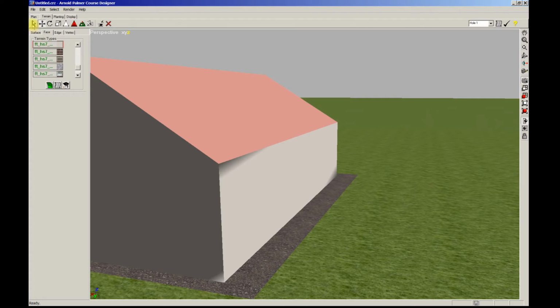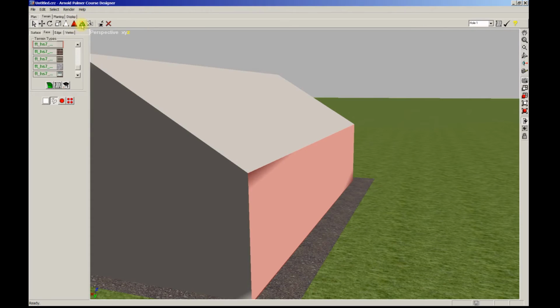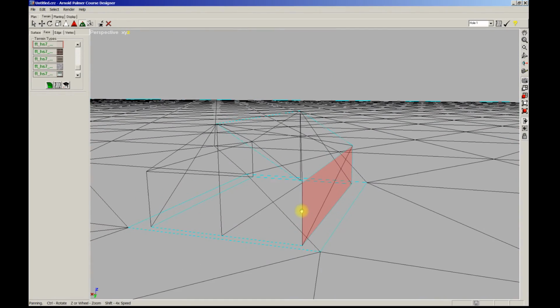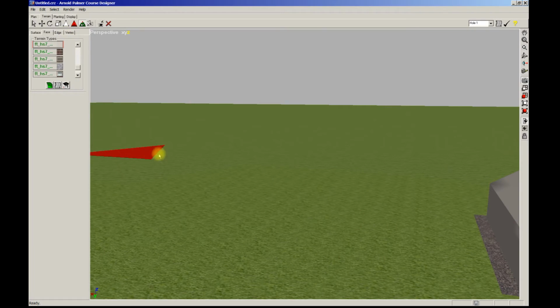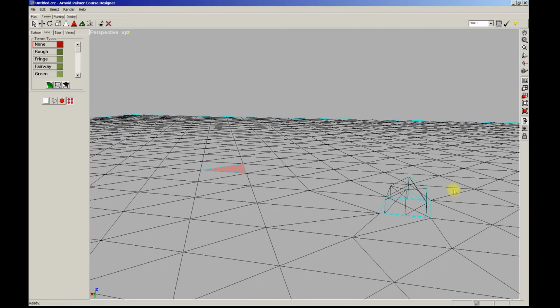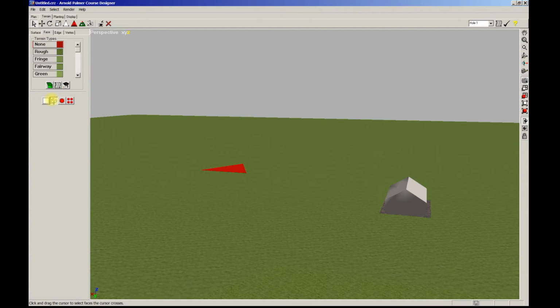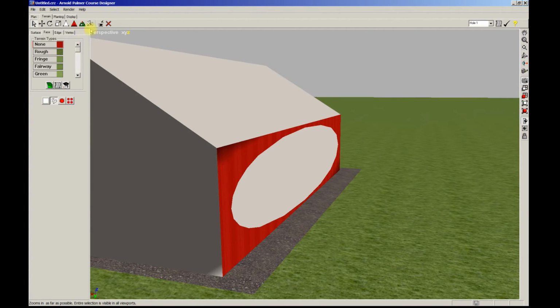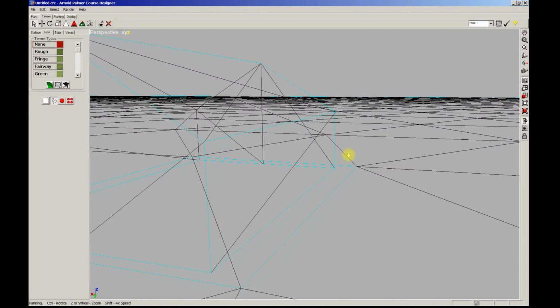Do one more real quick just to show you again what happens. I'll just select this side, extrude, tap it one time. Now I need to delete this red section. To do that, I got to go over here, select All of Type, select this, make sure it selected them both. It did. It put them both in the picture. Now turn off the All of Type, Control and deselect this, zoom back into it using this Fit Selection, and there it is. Hit the Delete button. That's gone.